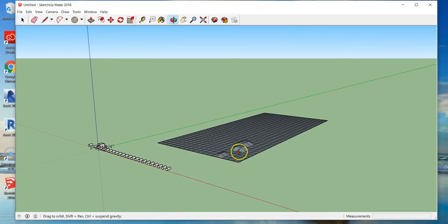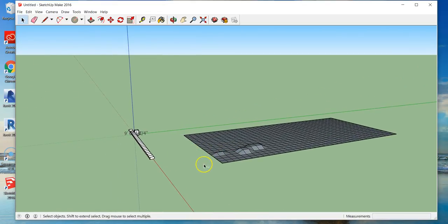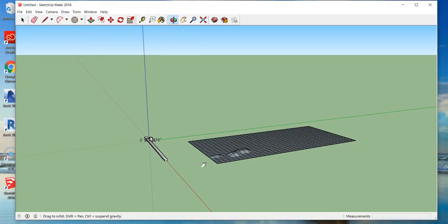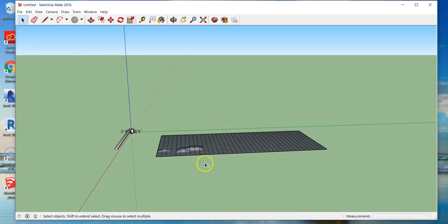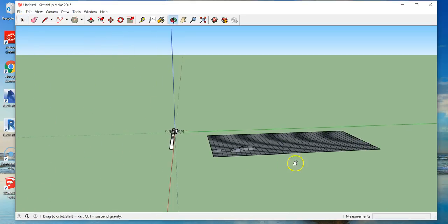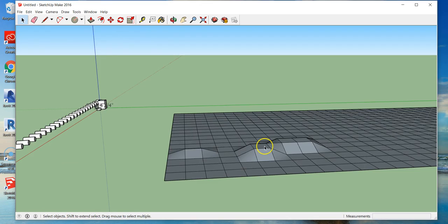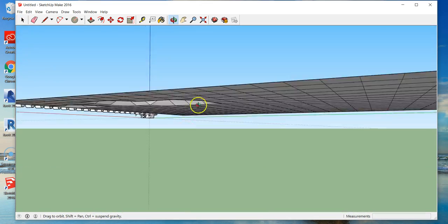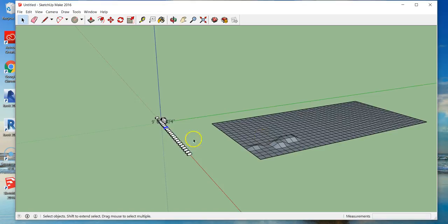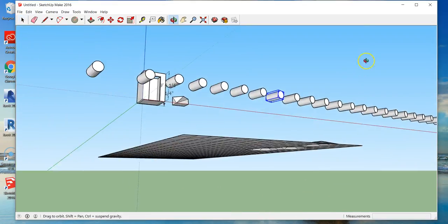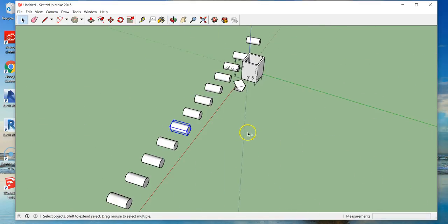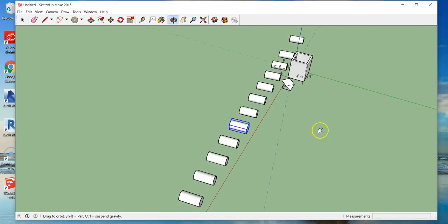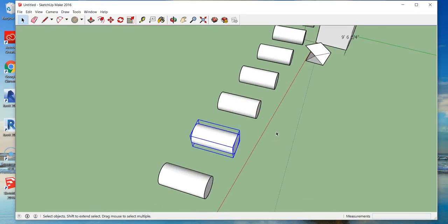Let's go around. So if you hit your center button, hold it down on your mouse, you can go around. If you zoom in and out, let's see, shift and the center button on your mouse is to pan, and then zoom out. So just your center mouse goes around. A lot of times, when you have a big model, I like to have something to click on, because then that'll be kind of its point of reference. And then Control and your center one is just pan, and then zoom in and out. You should be able to navigate all around it.